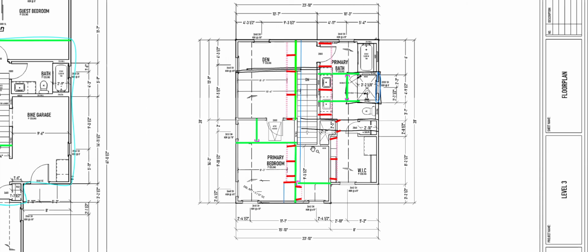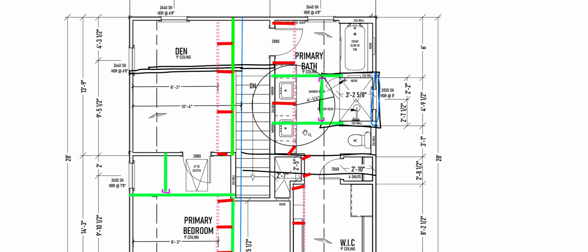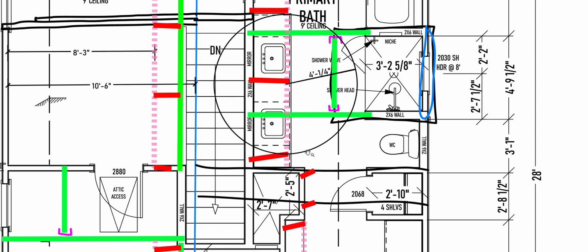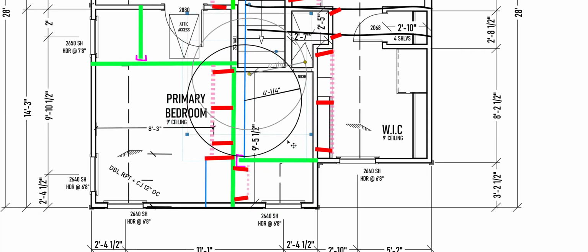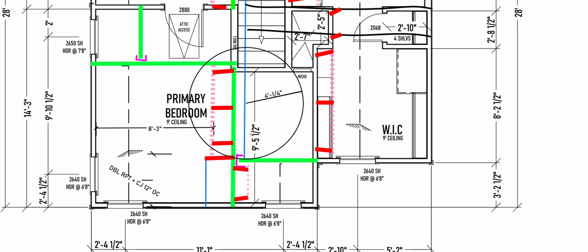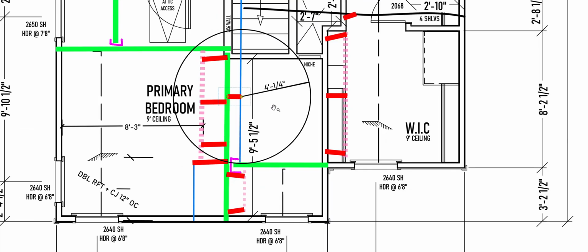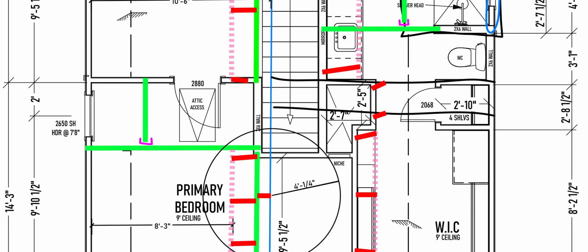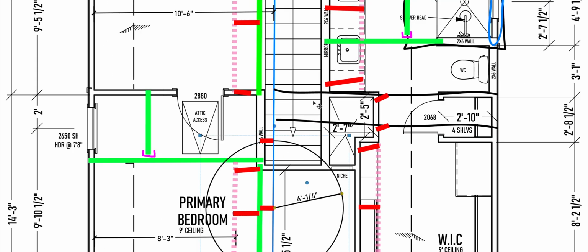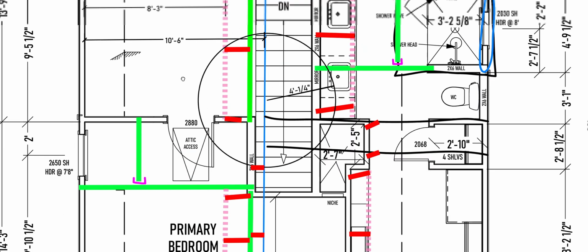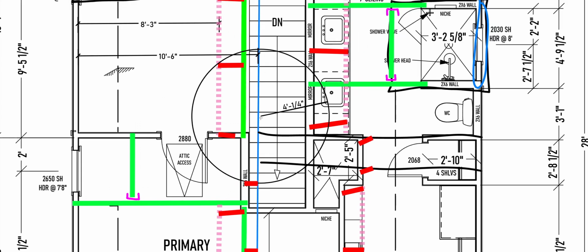I'm going to undelete that circle that I know I just deleted and put it where I want to use it. So 4 feet in from the start of my ridge, my first brace, boom, is going to go down to my beam. My next brace is going to go down to my wall, because the wall is just basically in the same spot as the beam in terms of height. And I'm going to keep going. I need another brace right here. So I'm going to brace to the wall because I don't want to put it on the beam if I can avoid it.